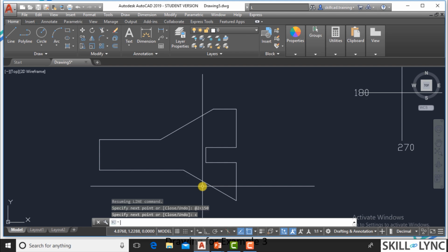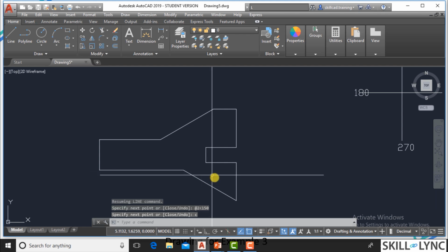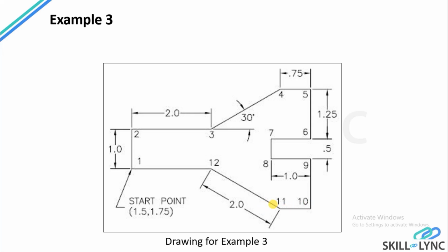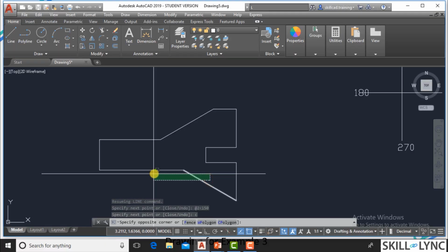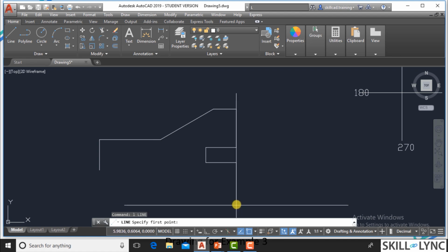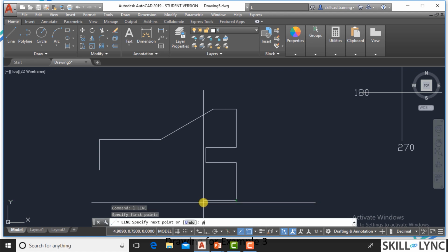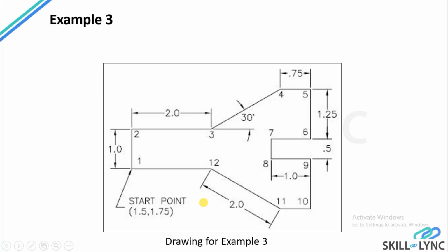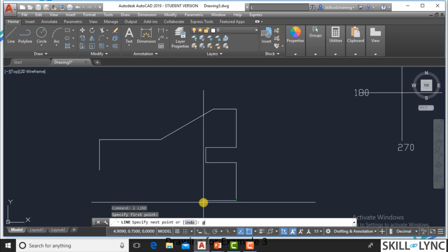Here the mistake we made is that we have to create this one again, so let me draw it from here. You can always pick the last point and say @. You can do it here at point 2, where the length is 1 unit, so you say @1 with the angle. Here you cannot undo. If you undo after finishing the command, the entire drawing will be gone.